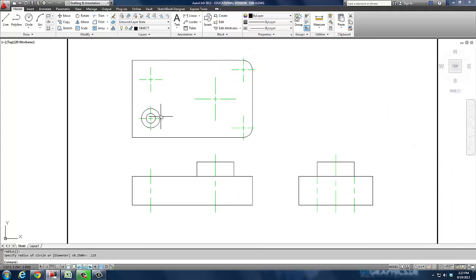So there he is. Now, going out from that, I know I have a circle that sits right in the middle here that is a diameter of 0.625. I've got another circle that sits on here that has a radius of 0.5, and then I know I've got a hole that goes through the middle of it that is at, if I double check my stuff on this, should be at 0.125.